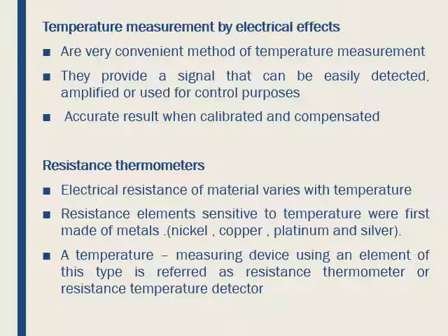The size of the capillary depends on the size of the sensing bulb, the responsive liquid, and the desired temperature range of the instrument. Changes in the temperature will cause the fluid to expand and rise up the stem. Since the area of the stem is much less than the bulb, relatively small changes of fluid volume will result in significant fluid rise in the stem. The length of the movement of the free surface of the fluid column serves by prior calibration to indicate the temperature of the bulb.